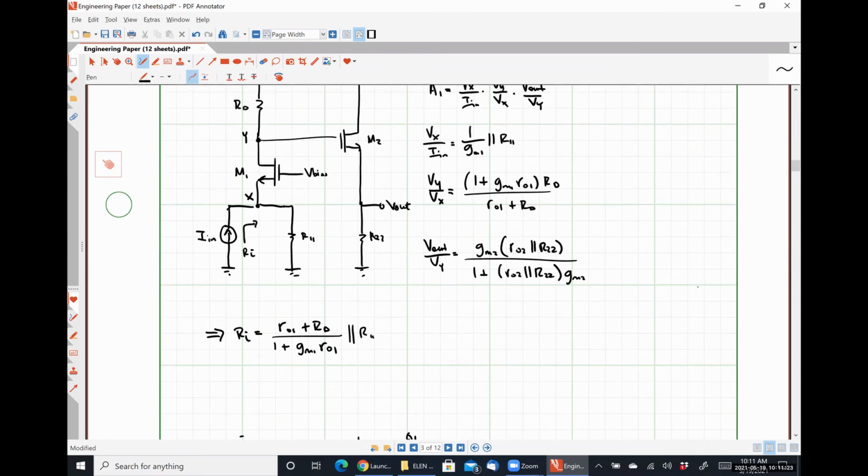So here's something that we haven't done in a while. We're no longer measuring a current at the output, so we don't need to break open a short circuit and look at anything. Our output resistance here is going to be looking in through the output terminal, and we're going to see whatever we see down in parallel with whatever we see up.